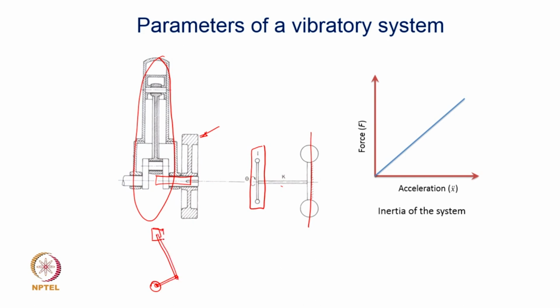So, the way to find out the inertia is to find out the kinetic energy of individual elements and find out an equivalent inertia, and we all know that the velocity of this piston and the velocity of this connecting rod at these positions are going to be changing each instant of time. So, the kinetic energy also fluctuates, and so the equivalent inertia that you can find will also change with time, and therefore, you cannot have a direct linear relationship between the inertia force and the acceleration.